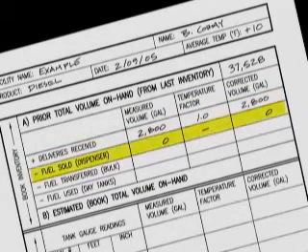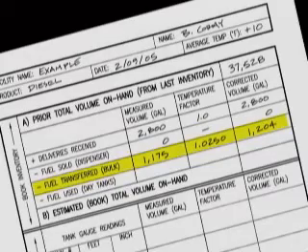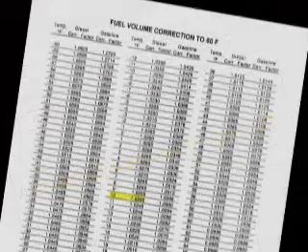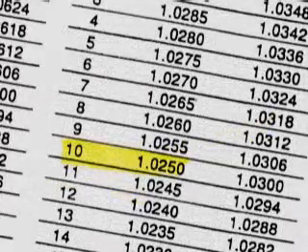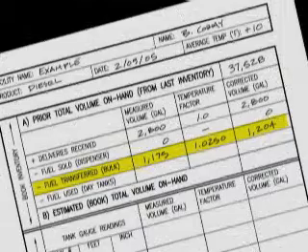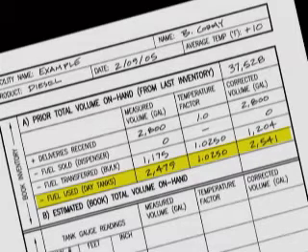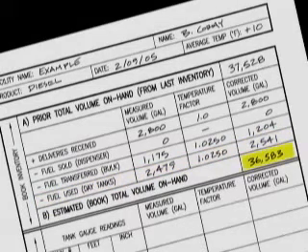The next line is for dispensing. In this case, there is no diesel dispensing at this facility, so there was no transfer. The next line is the bulk transfer. We had 1 truckload at 1,175 gallons. When the temperature correction factor for 10 degrees Fahrenheit is applied, this becomes 1,204 gallons. Next, the power plant day tank meter had logged 2,479 gallons during this period. Again, corrected for temperature, this becomes 2,541 gallons. The total of these is the estimated book total on hand.